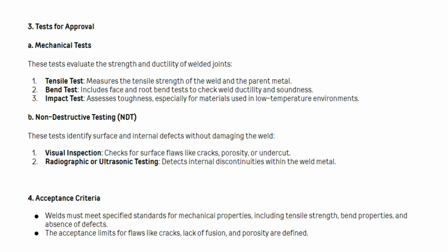4. Acceptance criteria. Welds must meet specified standards for mechanical properties, including tensile strength, bend properties, and absence of defects. The acceptance limits for flaws like cracks, lack of fusion, and porosity are defined.